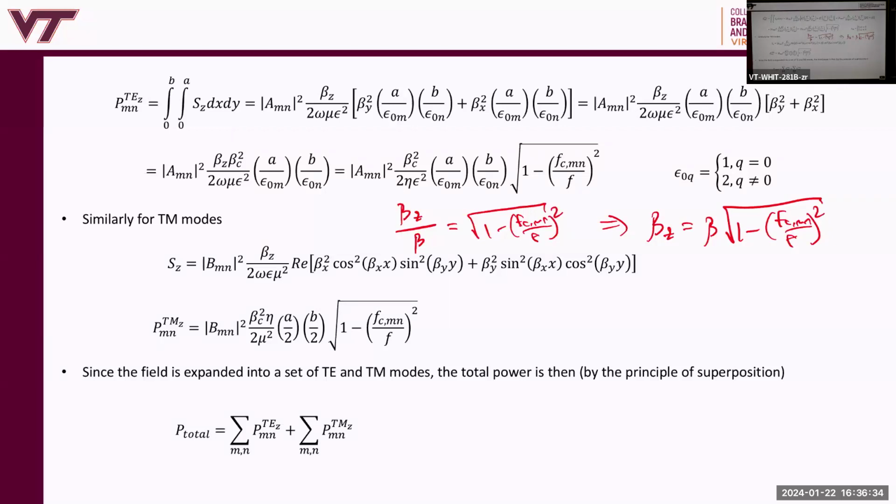And just how do we get that? Or do we just assume it's right? No. These are coefficients. All the coefficients are lumped, right? Now, these will depend on your source. So whenever you have an actual excitation into the waveguide, that has some power that you're launching into the waveguide, and you'll distribute that power amongst the modes like this, and you'll be able to calculate what these amplitudes are. I'll show you how to do that later, next lecture, as a matter of fact. How to expand fields due to probes in terms of the modes, right? We'll solve a coupling problem, which is not in the book. So if we're calibrating power and also trying to calculate the power, where does it start?